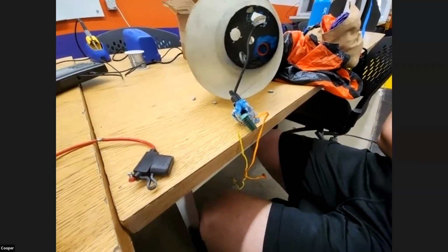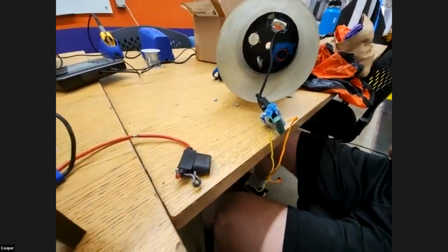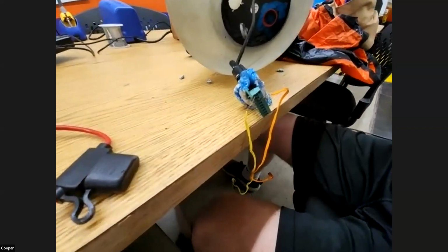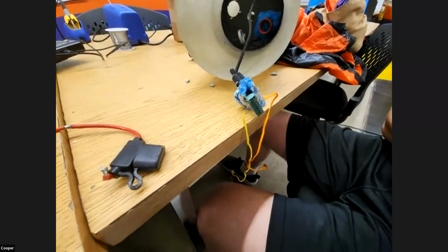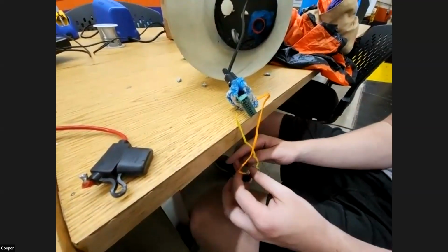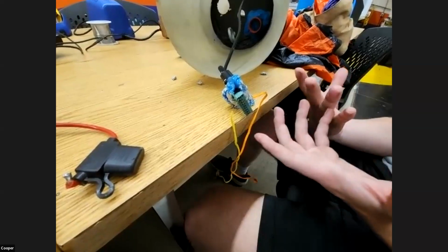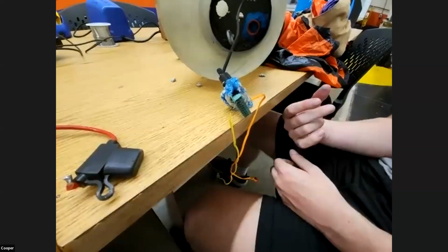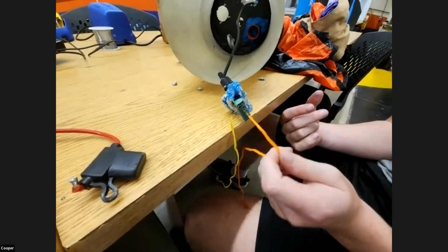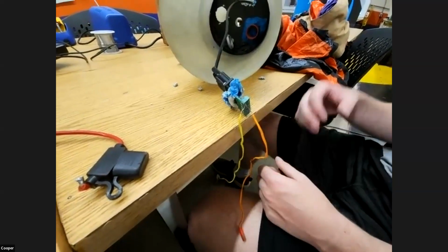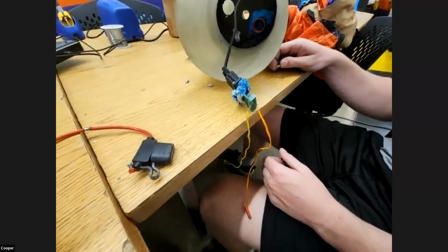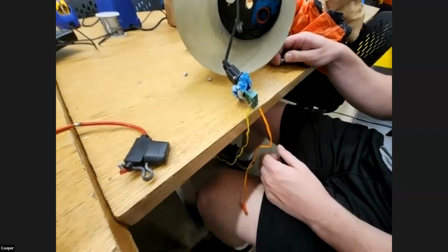The other piece is that all the wires coming out of that need to be in a bundle set up so that there is no flopping around. That's a key piece. And then the final test is to basically yank on them. Once you've got it all set up the way you want, pull on every connection point and make sure they don't accidentally come out. Okay. Sure. All right.